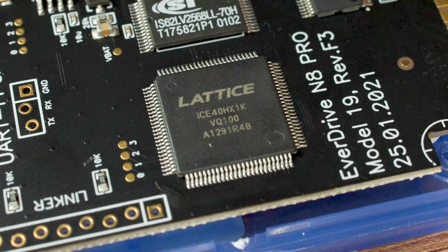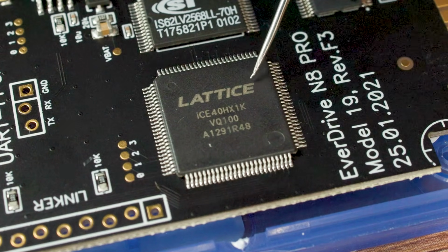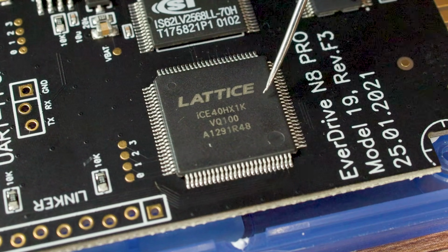And one other thing is this cartridge contains an additional, smaller ICE40 FPGA as well. I don't know why there are 2 FPGAs in here, but I'm guessing that maybe the Cyclone is dedicated to emulating the mappers, while the ICE40 handles the glue logic. I don't have a schematic, so I can't say for certain, but I suppose that would make sense.